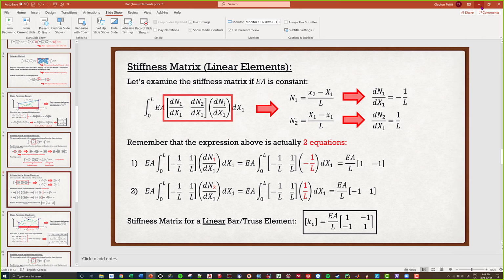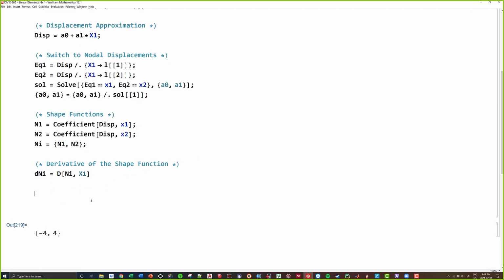So what I'm going to do is I'm going to come down, I'm going to go stiffness matrix. Now, question for you guys. Is this going to be the global stiffness matrix or the local stiffness matrix? Local? Local? Yo, you guys are on your game. Yes, this is indeed the local stiffness matrix because this is the stiffness matrix of the element itself.